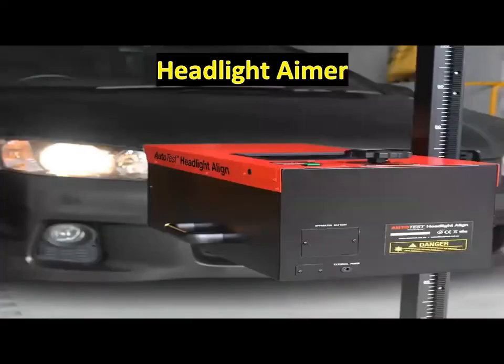Each adjustment rod setting on the aimer adapter must match the number on the composite headlight aiming pad on which the adjustment rod will be placed. The adjustment rod setting must be locked in this position. After the adjustment rod setting is completed, the aimers are attached to the composite headlights and the headlight adjustment is performed using the same procedure as for sealed beams.